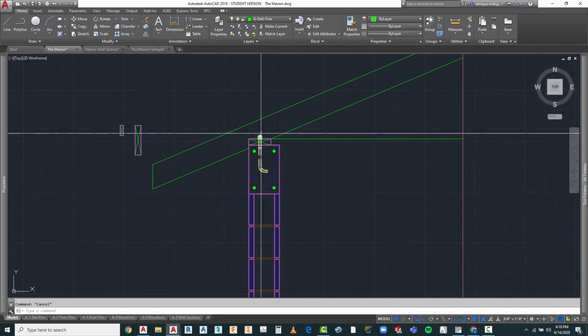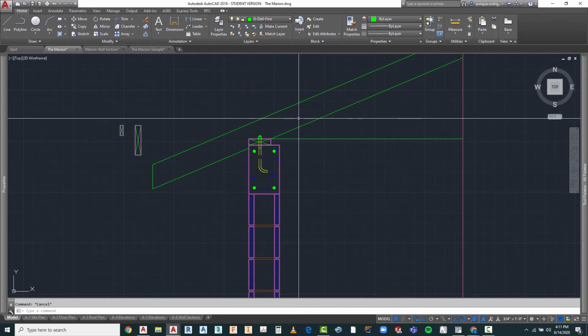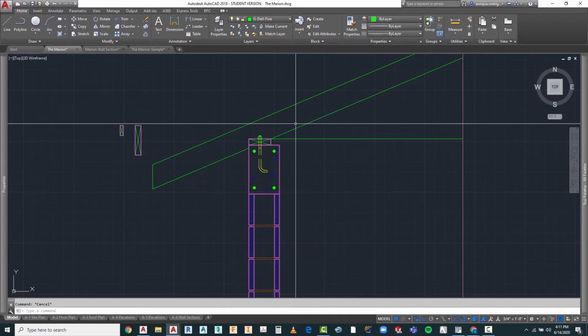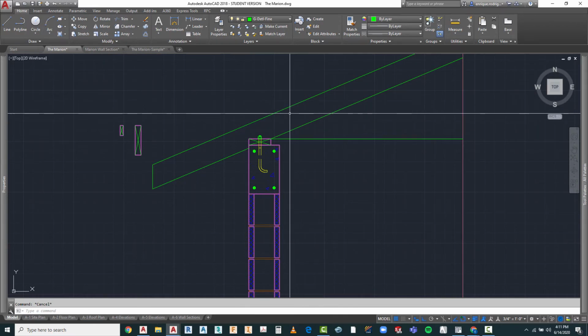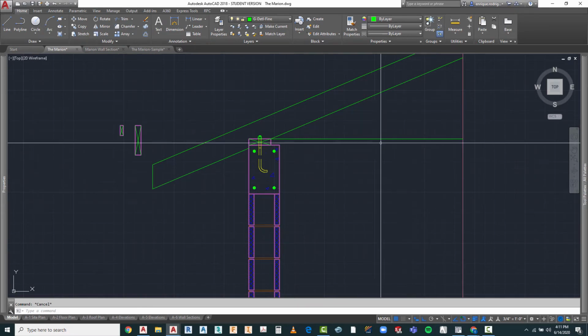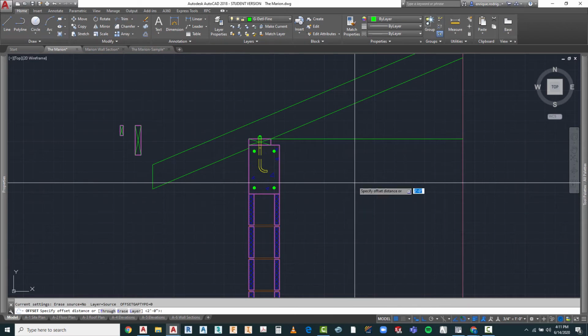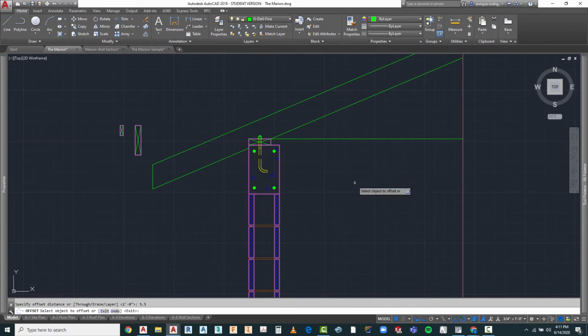at least when they rest on an exterior wall, they'll be located in the same direction, or they will be spaced at the same spacing that we have our rafters. Sometimes you'll bring them in at 18 inches instead of 2 feet, but that's not always the case. So I'm going to go ahead and offset this also, 5.5 for our ceiling joist.